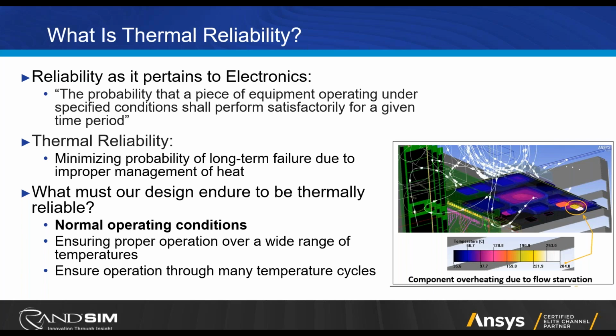After which, one can simulate the operation of a device as the ambient temperature around it varies. So exploring whatever series of temperatures is within your rating and simulating the design in those environments. And then lastly, going through thermal cycling, which can cause different issues as we will see in the following slides.